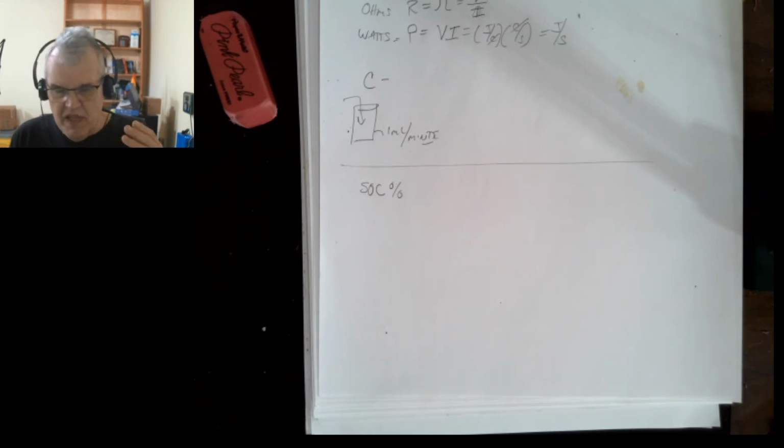Okay, all right. Just a couple more terms. Cycle life. Cycle life is how many times you can cycle the battery before its usefulness is pretty much used up. Now, a cycle would be from 100% state of charge to 0% state of charge. Each time you go to 100% state of charge and go to 0% state of charge, you damage the battery a little bit, right? It's like anything else. It wears down over time. So let's say for 18650 batteries, I think usually you see a cycle life of 500 times or 700 times. If you don't go to 100% state of charge and then down to 0% state of charge, you can increase the number of times you could cycle the battery significantly, maybe doubling it or tripling it or more.